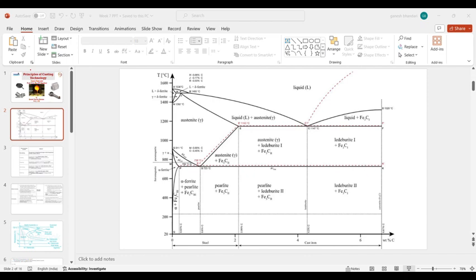In cast iron I don't think surface heat treatment processes are required, because in cast iron you already have very high brittleness, okay. So yeah, you generally go with steels only for surface heat treatment processes. We generally don't go with cast irons because they already have very high brittleness, so you don't want more brittleness inside the system, okay. So the answer is all of the above.